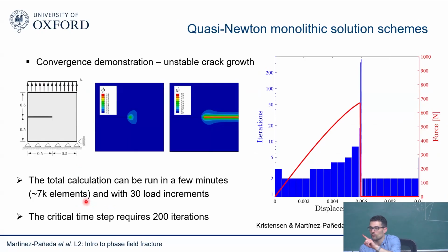One thing that came to my mind, the line search. When we started doing this work, we did it in Abaqus because Abaqus has it all implemented. We just touched a button and said, wow, this works so nicely, the BFGS. Then some people have tried since our paper to reproduce it in their own codes. I was told a few groups have managed to get this very good behavior, but you have to do it exactly as Abaqus does. So this particular BFGS implementation, and you need to put a line search, which Abaqus has already inbuilt as well. So that's one aspect.